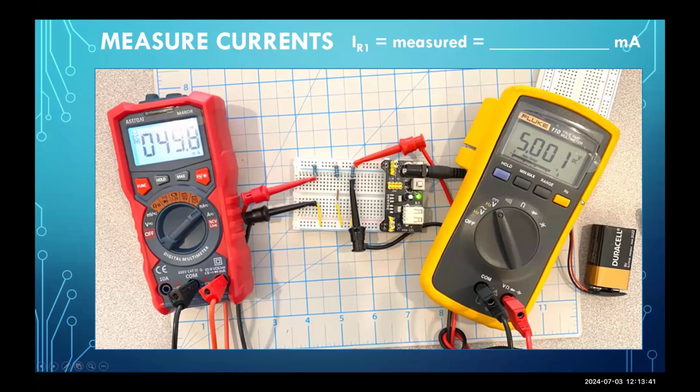Separately, I happen to have a separate multimeter attached to show that I've got 5 volts DC across the resistors. Okay, and interesting to note here, I'm not using a USB for power. I'm using a 9-volt battery with battery clips onto a barrel connector. And what I like about this is it reduces the number of heavy cables across my workbench and makes this board completely portable with a 9-volt battery and a barrel connector.